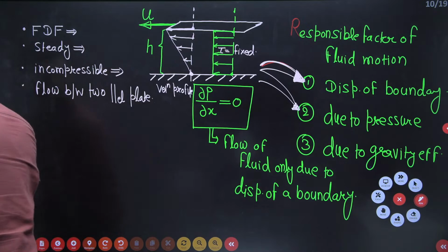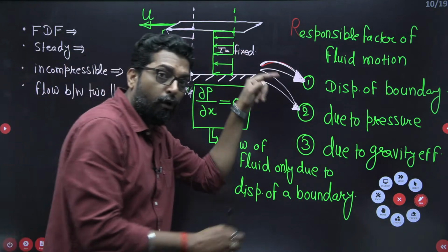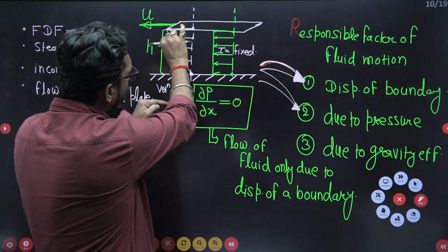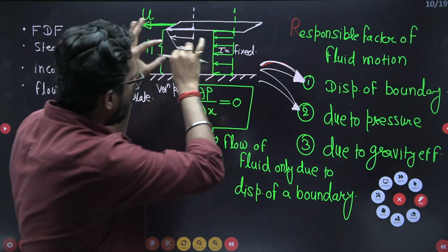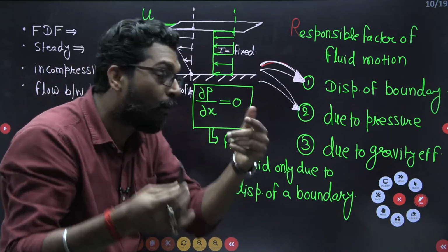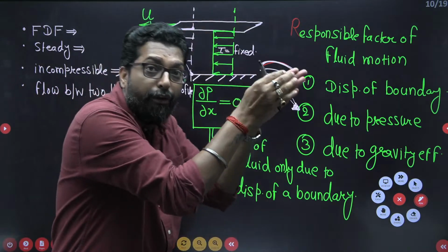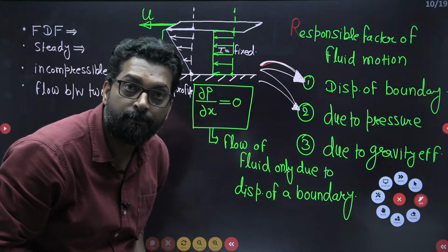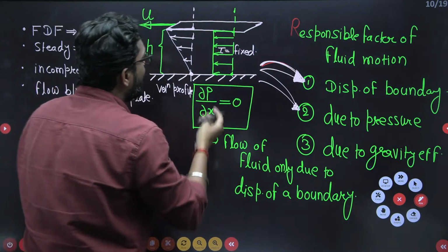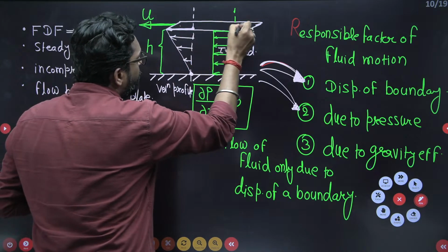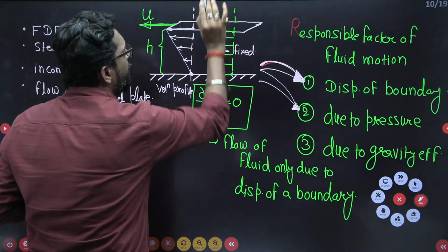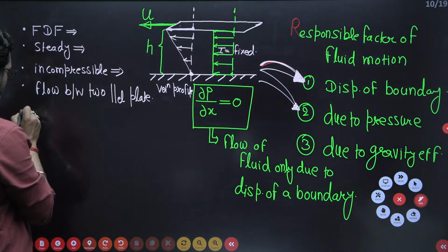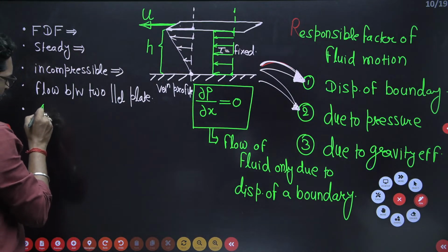Now, my dear, the fluid is flowing in this direction. Perpendicular to the flow direction, the velocity is 0. Why? Because the width of the plate is very large as compared to the length of the plate. Okay, number first. Number second, there is no penetration in the plate, so there is no velocity in the vertical direction. That means this must be a one-dimensional flow.